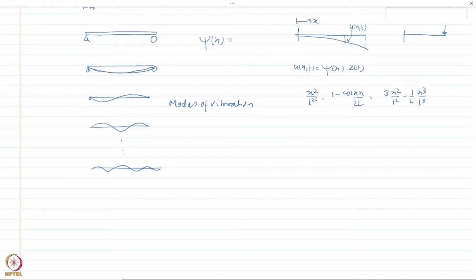Now, as I've told you, I'm not trying to determine the exact mode shape, which I could if I did the multi-degree of freedom analysis using a large number of modes. But here, my goal is to do it without having to get into all the mode determination. So I'm going to assume the deflected shape to be one of these functions. Now these functions, as you can imagine, would provide approximate results, and whether that approximation is good enough depends on the shape function that you have selected.